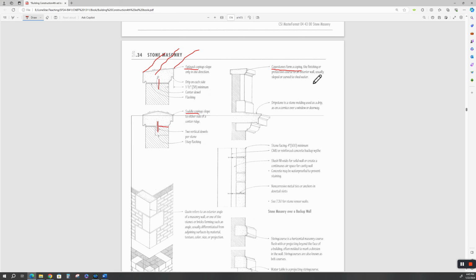Finishing a protective course on all exterior walls. And depending on the building and the masons that built it, they would get pretty elaborate. They'd have this support coping here. Then they'd have a drip stone up here. This is called a drip stone, as you can tell, because the water would come down and drip off of this and fall down. And sometimes these had ornate stuff cast in them or carved in them, if they were traditional stone.